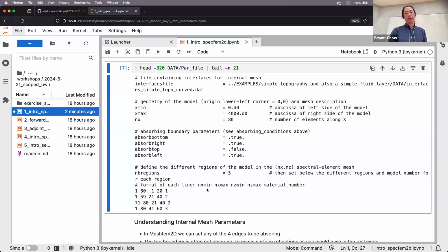And then for your question, you can see here the regions that we're assigning at the bottom. So we want 5 different regions. And this is defining them by the element number. So you can see different layers here where we're taking spatial coordinates and we're assigning them some value of a region so that we will then assign velocity model values to.